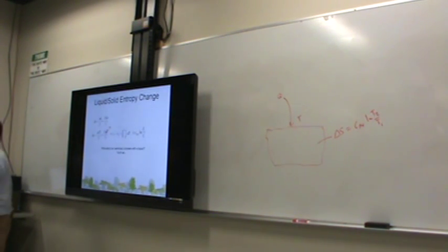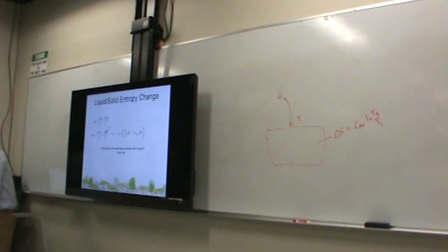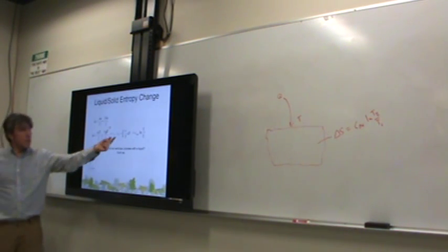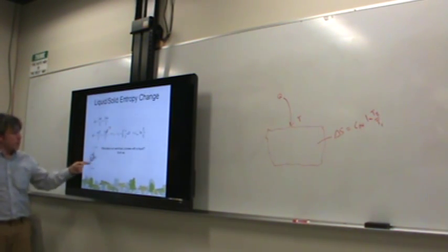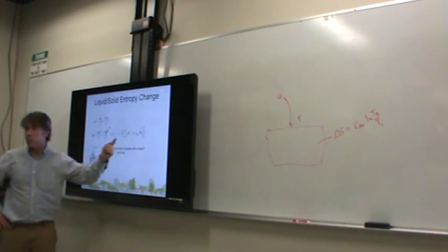What else could we do with this? What about an isentropic process? What if there is no change? What if we know that there is some kind of system that should have no entropy change across it? Such as what? Well, such as a pump. If you have a pump, ideally it would work best when there's no heat transfer and no friction, right? When it's reversible, okay? So in that case, the entropy change from inlet to outlet, from state 1 to state 2, would be 0. That means that this equals 0, right?